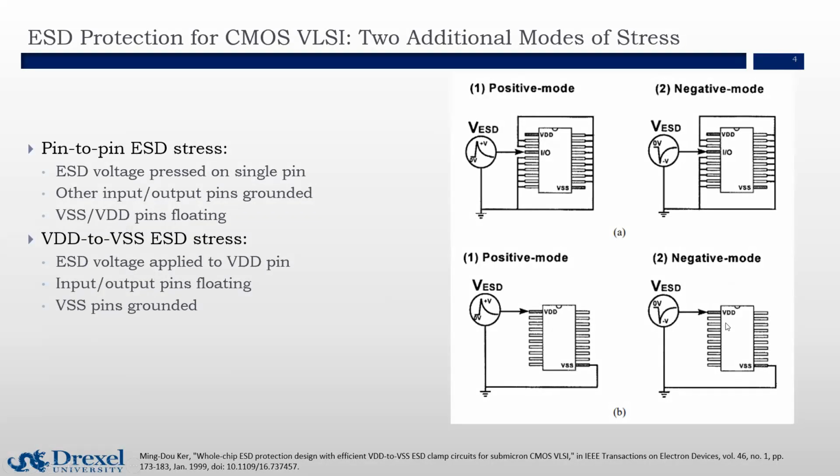Also, we can have 2 additional modes for ESD protection. The first one is pin-to-pin ESD stress. So ESD voltage is pressed on a single pin, with other input pins and output pins grounded, and the VSS and VDD pins are floating.